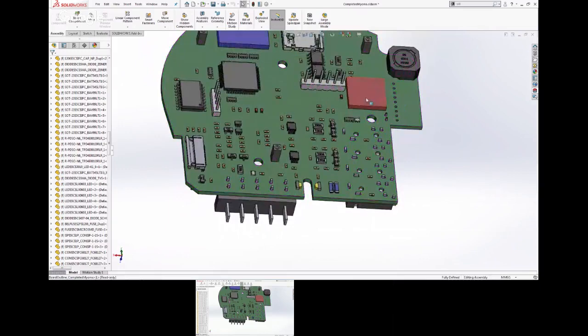Yeah, this part here, I just left it. That's what you'll get as a generic shape in Altium Designer, some geometry with height, because I care less. But if that's one of the most critical parts, maybe I need a nicer representation, like this inductor here. That's very critical because it has a height that I'm going to check against the enclosure. So the mechanical side wants to see that precise model. So we're going to go ahead and embed the solid part, and it's going to build it and come to you in your mechanical environment.